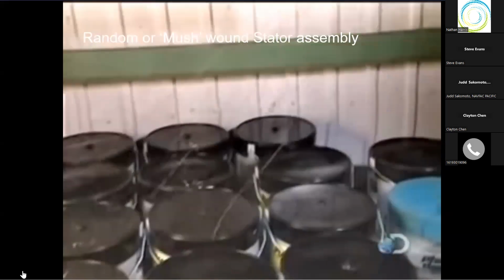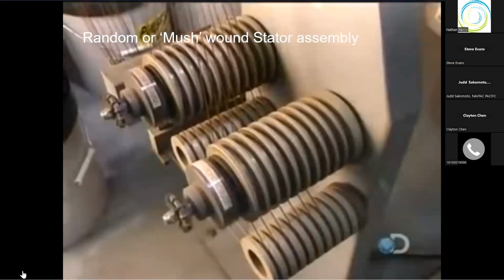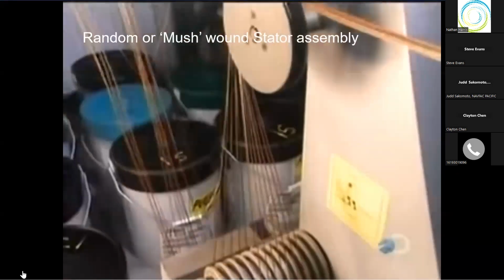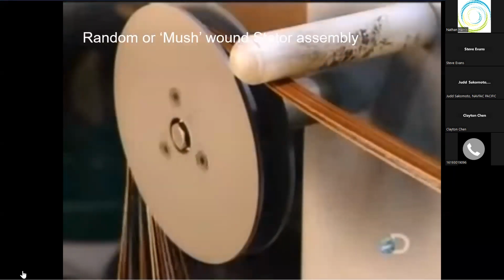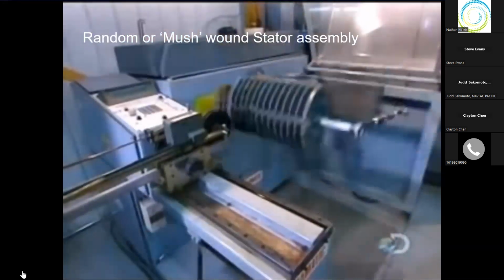The coils are made from several copper wires wound together by programmable machines. The bigger the motor, the more wires per coil. Each wire is insulated separately. Varnish. In this motor, each coil consists of 13 strands of copper wire.